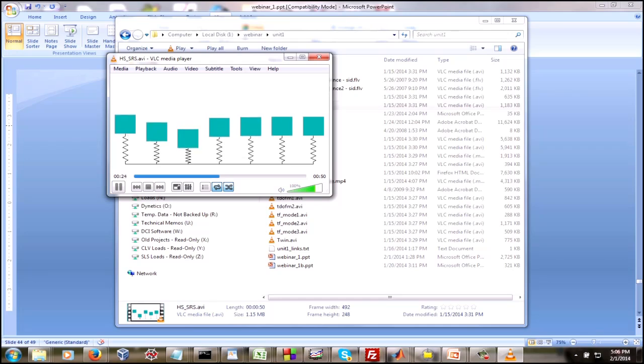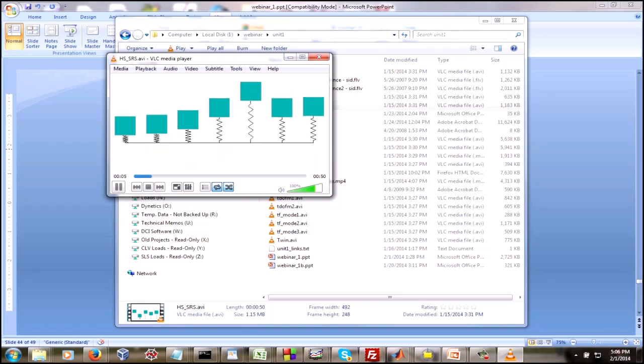And that's all well and good, but we need to make sure that the isolator can withstand the expected maximum relative displacement without bottoming out. So bottoming out is one concern anytime we isolate. We also may be concerned about sway space and clearance and whether or not this mass might have an impact with some other nearby mass or subsystem or component.